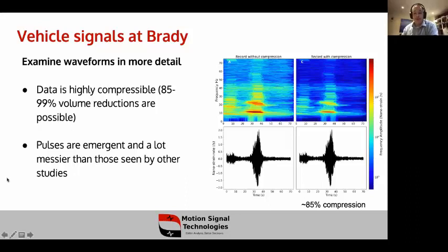So firstly, there's details in the TLE paper of the compression algorithm. In terms of what I mean by it, it is the number of bits that are required in order to store this particular waveform. So the one on the right, if you store them as standard 4-byte floats, or even 2-byte differences, you can treat them with the compression algorithm, which is based on a wavelet decomposition. I should point out, it's a lossy compression. You don't get anything for free on this, but it does at least preserve most of the signal.